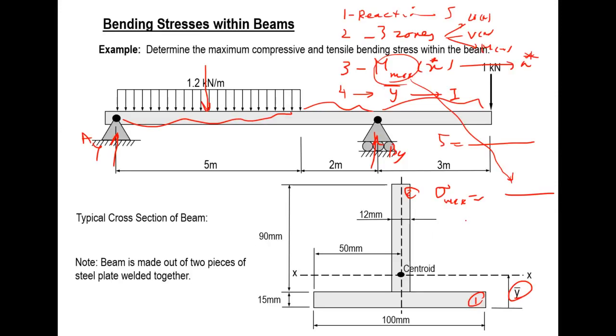So if my Y bar is equal to 30, can you tell me what is Y star? The point at which the maximum distance from the neutral plane is. So my neutral plane is 30 millimeter from the bottom. So which point is more critical? The points which are at the top or the points which are at the bottom? Which one are more critical?